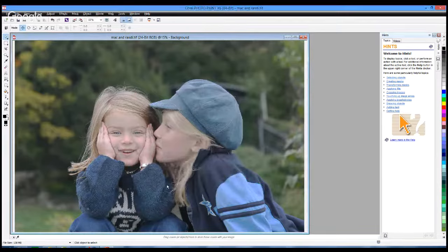The biggest thing to get over for a lot of people when you're working with photographs, when you want to laser engrave them, is you actually end up making the image look very bad on the screen in terms of detail. But it's that minimal amount of detail that allows us to get a good looking image on wood or acrylic, because that product doesn't show a good detailed image. So because it doesn't show a good detailed image, then we need to give it an image that doesn't have a lot of detail. It sounds a bit like an oxymoron, but ultimately this is the way that we adjust. If I'm printing out to a full color printer, then I may not make the adjustment because the printer may actually show the detail in the colors that I want.